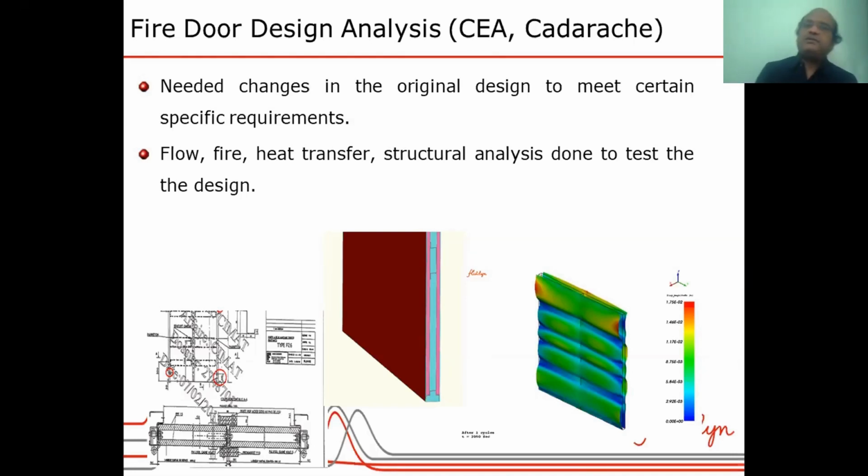But after that, there were certain changes in the adjoining rooms. That is another aspect. The fire load in case of an accident is evaluated based on the possible sources of fire in the rooms. So if a new equipment comes into a particular region, then its effect on all the neighboring safety systems is to be immediately considered.